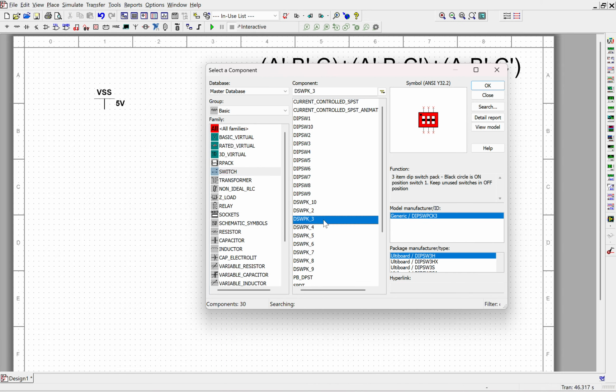Now looking at our Boolean algebraic expression, we can now start to look at what gates we're going to need. Click on your place MISC digital, and we're going to start with expression number 1. So this is not A, not B, and C. And we're going to start with some NOT gates. So type in NOT, and we're going to put them across here. So that's going to be not A, not B, like that, and then C is on its own, so you don't need to worry about C.